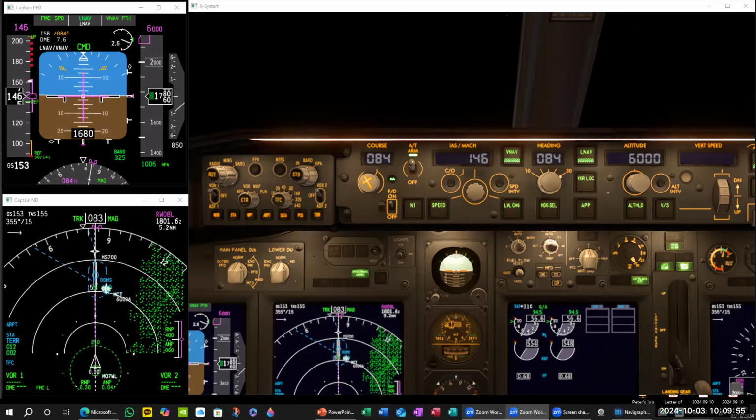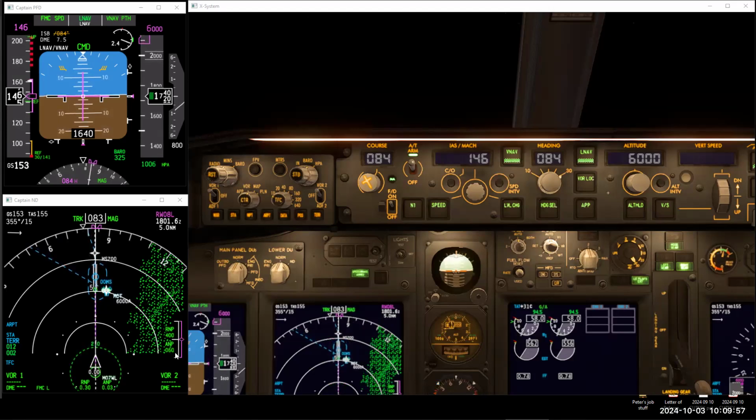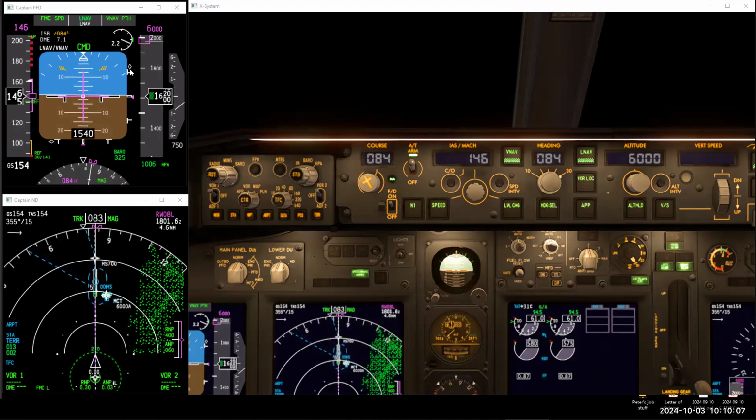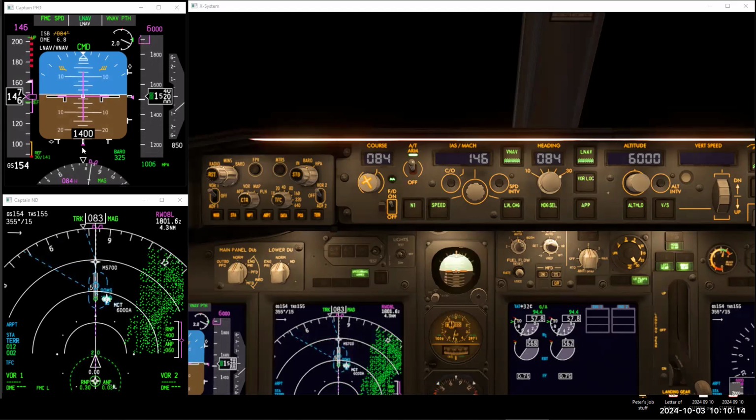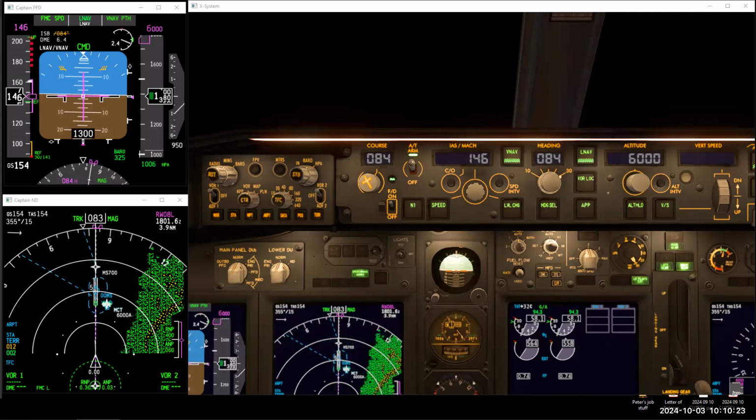Looking at our RNP, AMP against the RNP, we're within 60 feet. AMP and the RNP is 400, looking good. And the actual track, this little symbol here and this little symbol here shouldn't be there. That's just a simulator glitch. But this is the actual nav performance track, as we talked about, and this is the actual path that we were looking at, which is the 3.1 degree path. Rate of descent is good for our speed, so everything checks out okay.